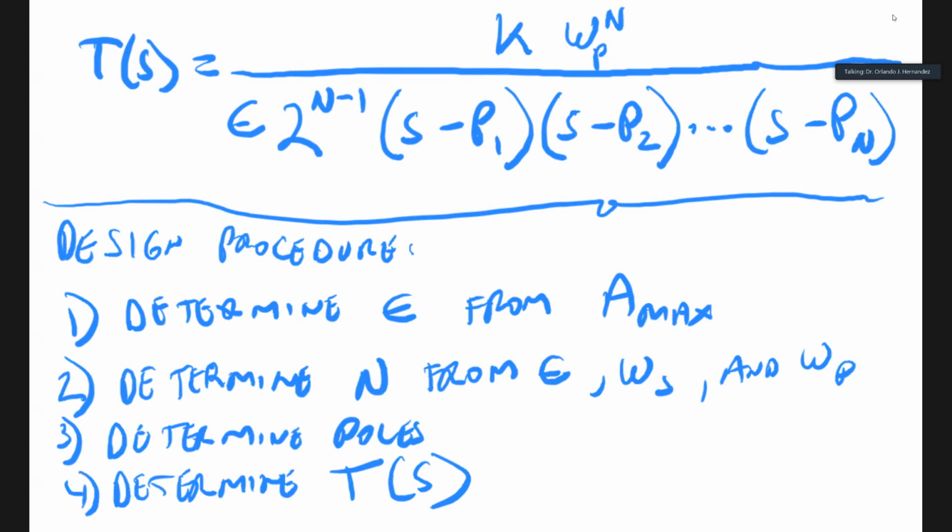The fact that if you want the high pass, you can basically subtract the low pass from 1. In this case, this is an all-pole filter, so specifically they are not good for bandpass necessarily, but you can get a high pass by subtracting the low pass response from 1. So that is the Chebyshev filter, specifically the low pass.